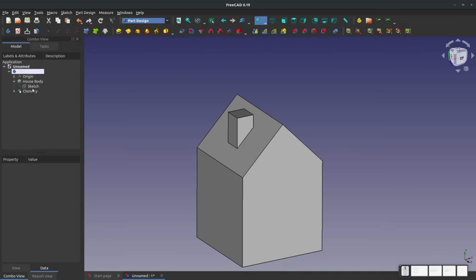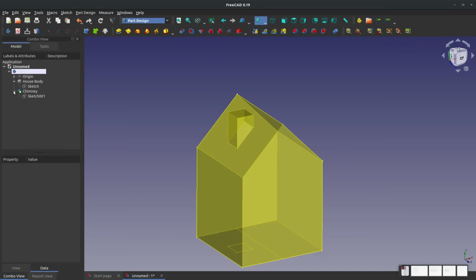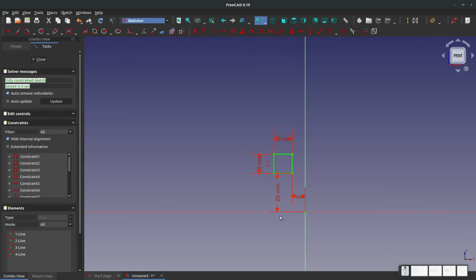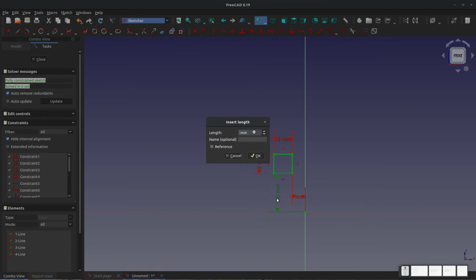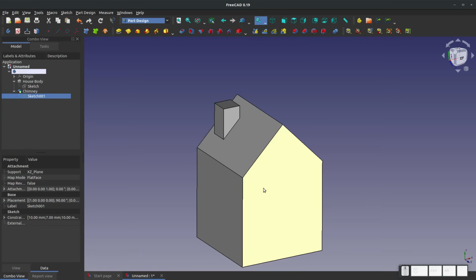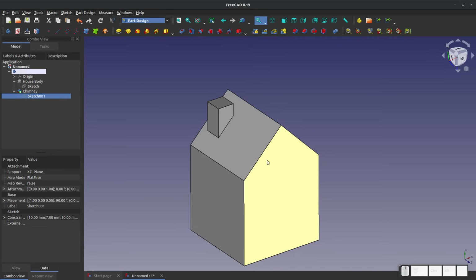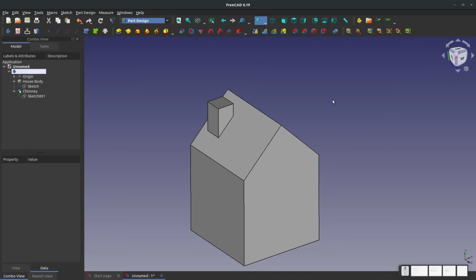So that's how we do our parametric modeling. We can go back into the tree and change certain parameters, right? Maybe I want to change the location of my chimney, and I can make this, how about 5? And that will move the chimney to one side of my house. So that is how we can do some modeling where we're not just sculpting clay, right? Blender is known as a direct modeler and it's great for animation. But for engineering, we have parameters and we need to change all the parameters. And so this tree gives us access to make the changes that we wish for editing parameters.